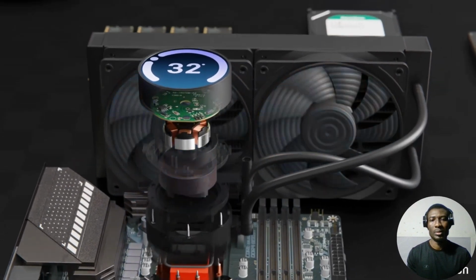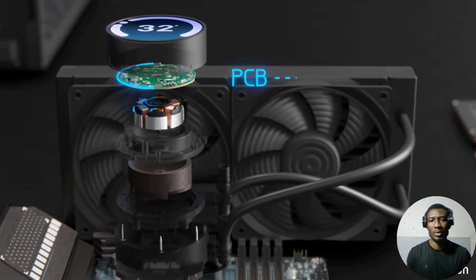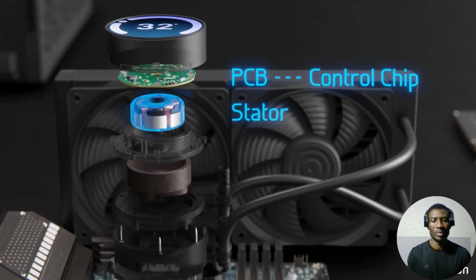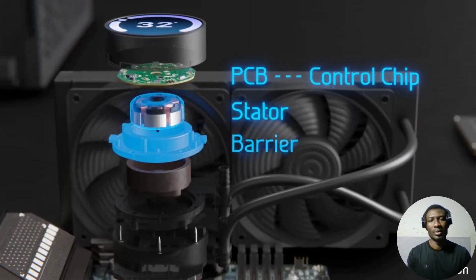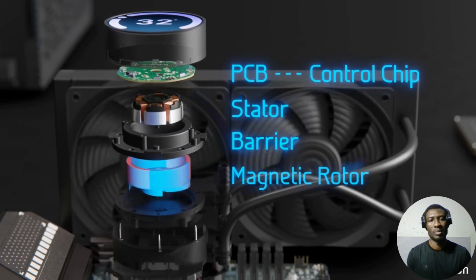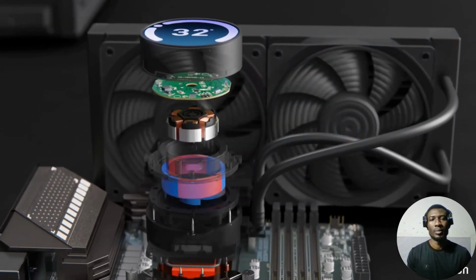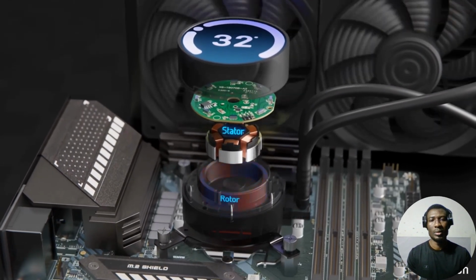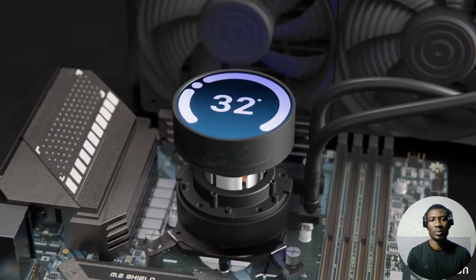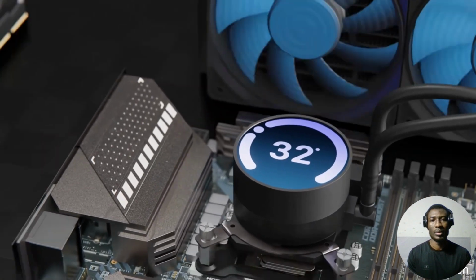The pump is a brushless DC motor, constructed from a PCB, a control chip, and a stator on the dry side, a barrier in the middle, and then the permanent magnet rotor and impeller on the liquid side. There's no mechanical connection between the rotor and stator, thereby preventing any leaks of the cooling liquid.